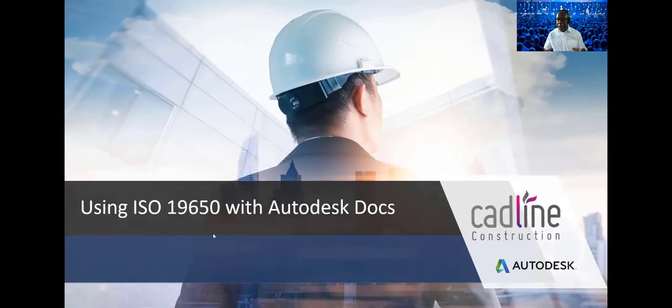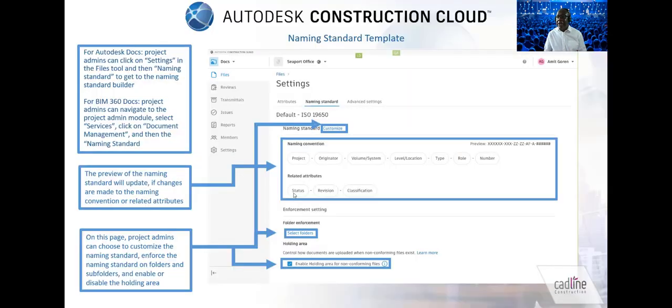The ISO 19650 compliance with Autodesk Docs. So this has been a long-awaited addition, and it says for Autodesk Docs, project admins can click in Settings in the Files tool and then Naming Standards to get the Naming Standard Builder. For a BIM 360 Docs project, admins can navigate to the Project Admin module, select Services and click on Document Management and then the Naming Standard.